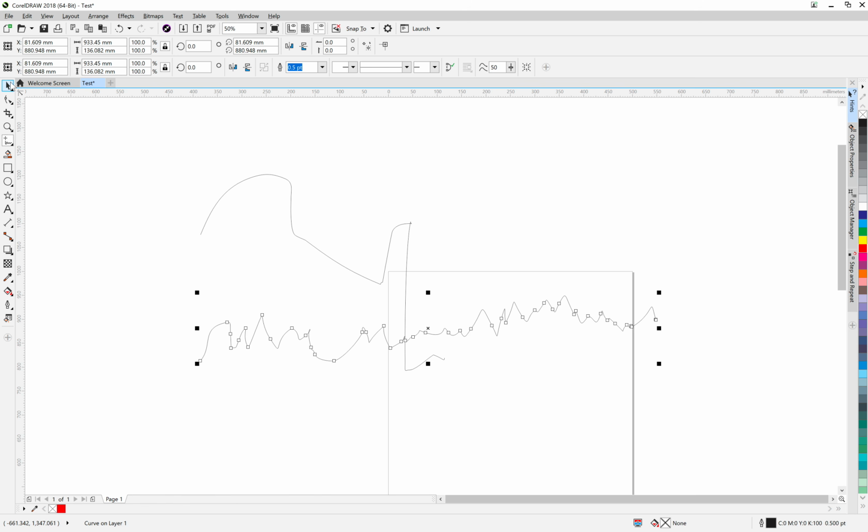That's very, very important because one, it smooths the object, but two, if you're cutting a vector image on a vinyl cutter, the last thing you want is loads and loads of nodes, because every time the blade follows the path all the way around on a cutter, it has to stop and turn, stop and turn, stop and turn. So you may see later on when we do some traces, loads and loads of nodes, and you just don't get a smooth cut. It's also very slow to cut, so you need to reduce that as much as possible.